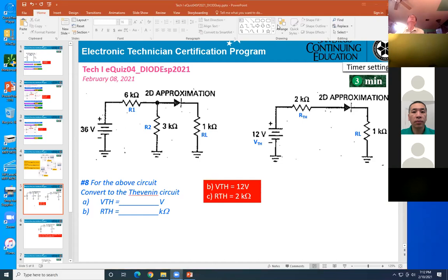Can I ask a question real fast? Now, for this circuitry, if you want to calculate the V Thevenin, what can you do? Who still remembers that? If I want to calculate the V Thevenin, you take off the load, get rid of the RL. Yeah, very good. You take that out, right?